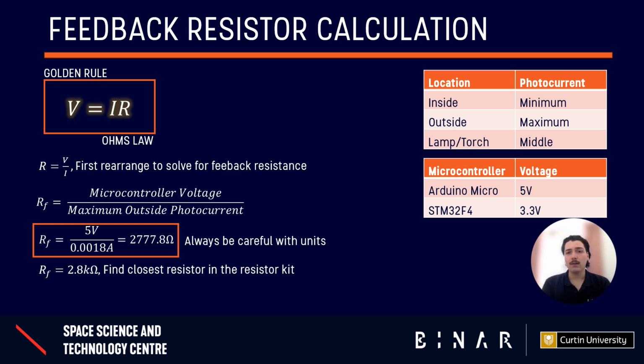However, when rounding, we need to consider whether rounding up or rounding down is better for our needs. Rounding up increases amplification, but might cause our readings to max out too quickly, whereas rounding down sacrifices some sensitivity, but allows us to measure a wider range of light intensities. Therefore, if we're recording light levels over time, rounding down might be the better choice to avoid saturation.